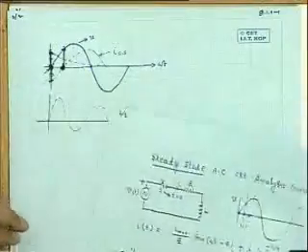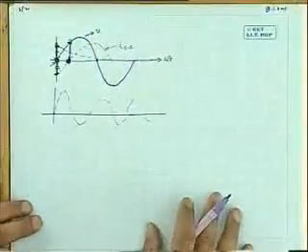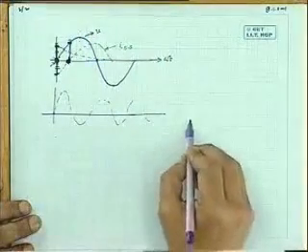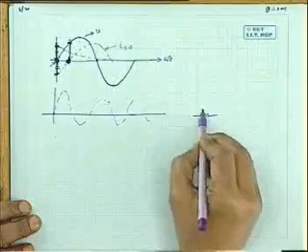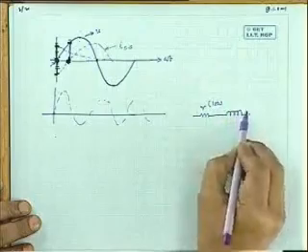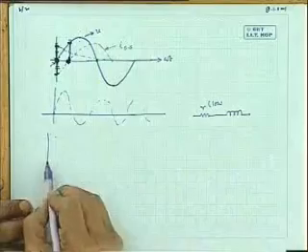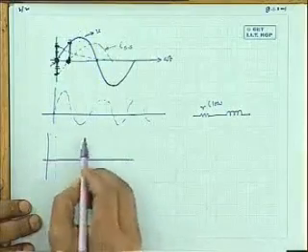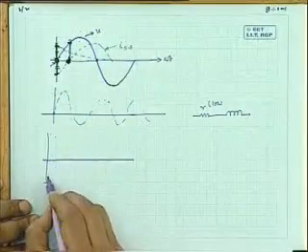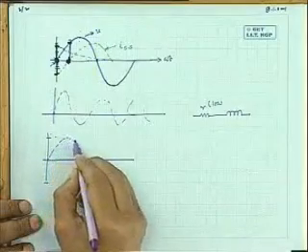Anyway, this has some far-reaching implications in some circuitry. For example, I will tell you just one example. Suppose you have a circuit whose R value is very low, and the inductance value is large, such that the steady state current in the circuit will be practically lagging the voltage by 90 degrees.